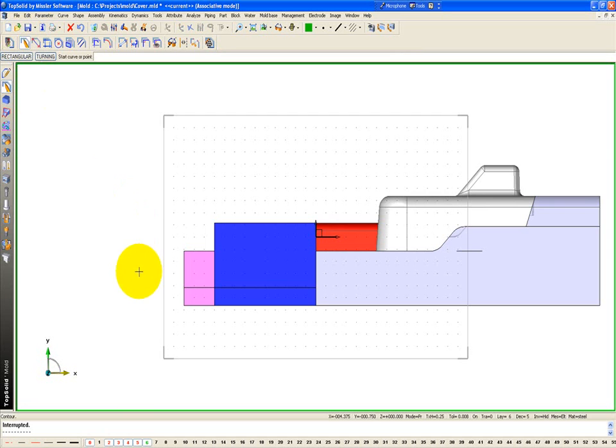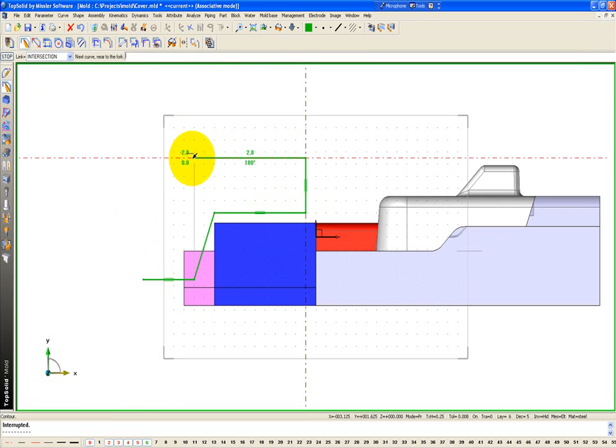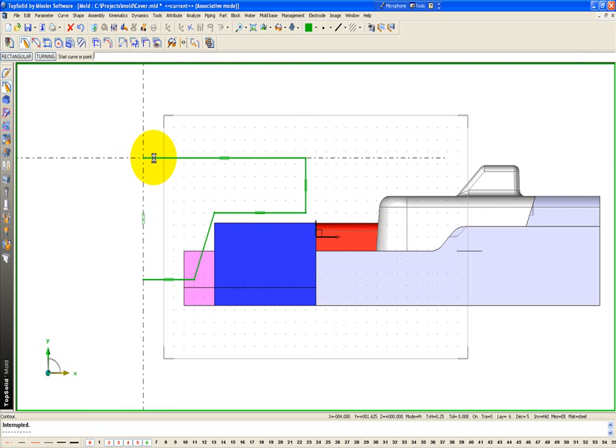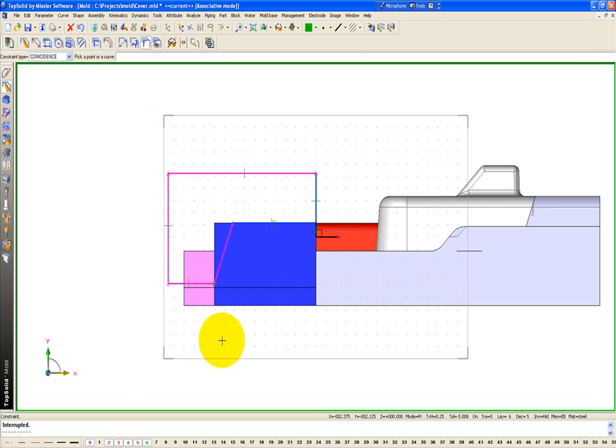So here I'm going to start a new contour. I'm going to come up, come over. I'm going to come up some angle, come over some distance, up some distance, over, and done. Okay? And now I'm going to add a few dimensions and a few relationships. So I'm going to start by adding my constraints. I want that coincident with that edge. I want this with my y-axis. I want this on this edge.